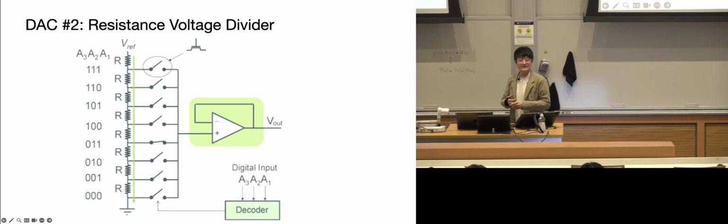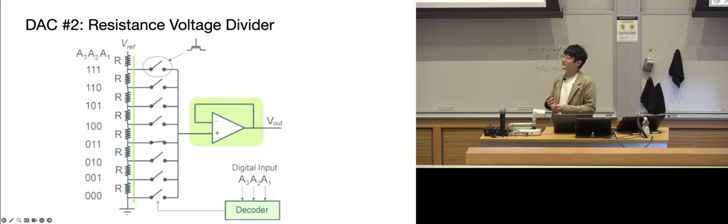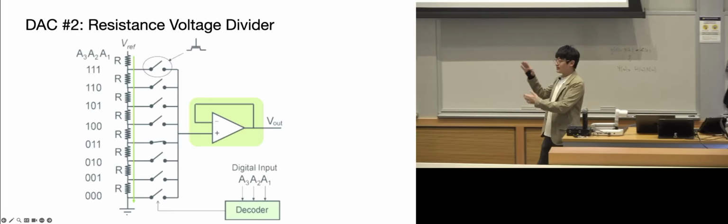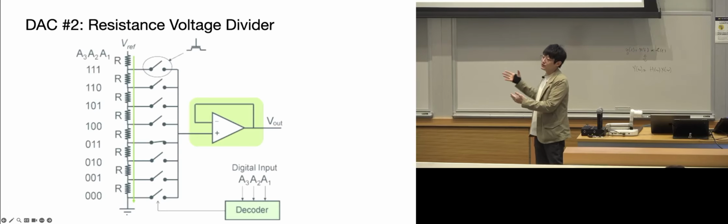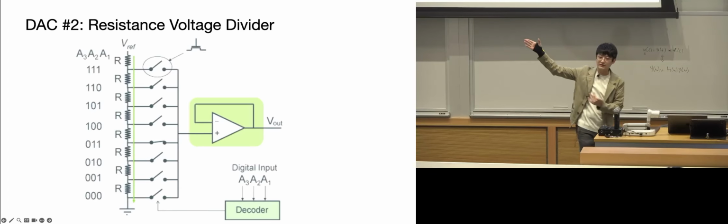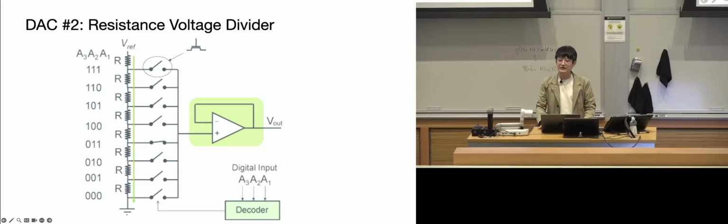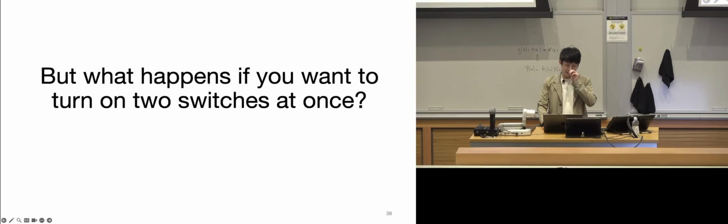Any other thoughts? Yeah, I think that's mainly that. Also, it's just not very scalable, because of the space it has and the amount of resolution. So the time resolution will be very high for this one, but the actual voltage resolution of your output voltage is quite limited based on the amount of components you're willing to throw onto this configuration. So it essentially increases to 2 to the n, which is not ideal, but works.